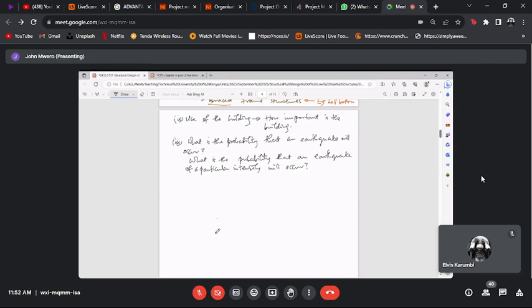So you go back to history and say, what is the history of earthquakes in this area? And what are the intensities? And then, of course, using statistics again, you would be able to predict that earthquakes of intensities of this magnitude are likely to happen within the next 50 years or 100 years. So if your design life is 50 years, then there's a probability that a certain earthquake intensity will occur, and therefore you design for it.